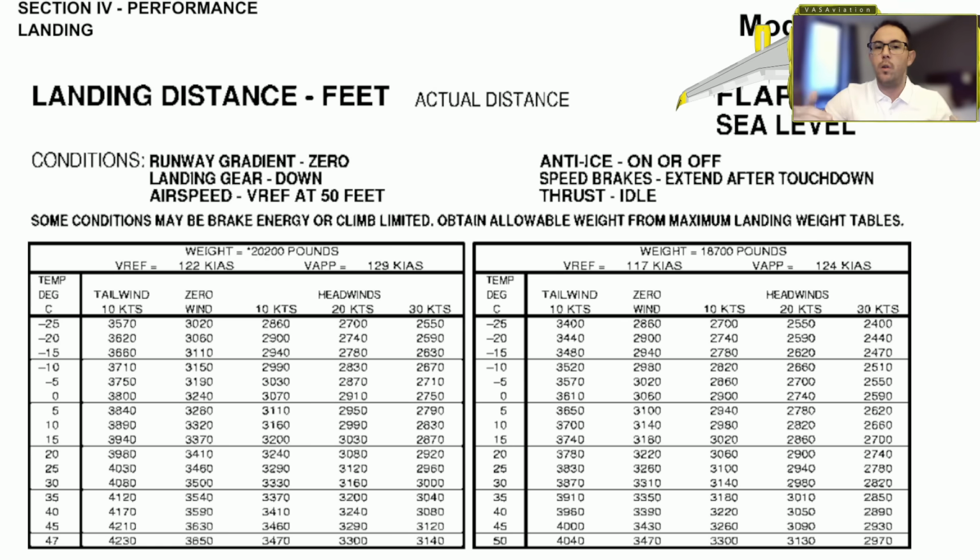You can take more fuel on the ground, but you cannot take any more weight to the air. This is the maximum weight that your aircraft can fly with. So only in that case, and we need to return to land, our VREF will fall into the category C. I don't know if in that situation we will take any minimums to category C, or we will just, of course, go ahead and land right away. But just so you can see the difference between both airplanes, only in an emergency situation we would fall into the category C on a Cessna Citation XLS.